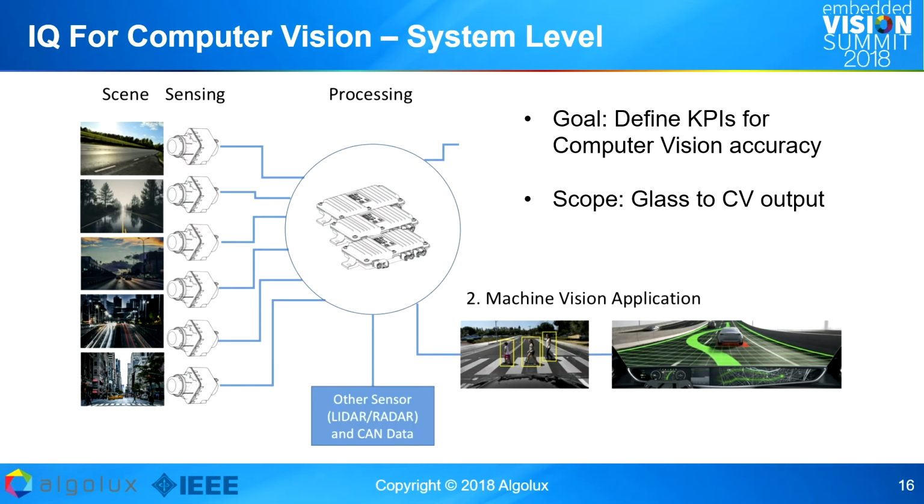And so this is an interesting subsystem that gets characterized in P2020. So rather than looking at a system completely end-to-end, taking the incoming light field, propagating it through the windshield, lens, sampling on the sensor, ISP, then the computer vision trunk, the system looks at the front part. It only looks at the part which can characterize all the way from the scene illumination to an output by an ISP system.